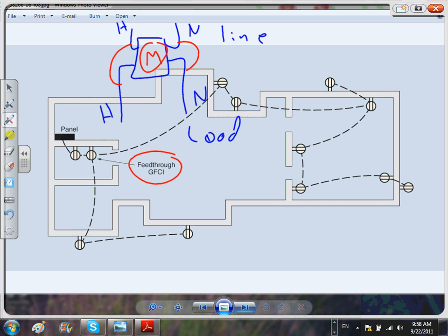At the time, it wasn't finished. Now it's completely finished, and there's a GFCI receptacle, and there's equipment behind it. From that GFCI receptacle in the basement, he fed through a receptacle outdoors, which is okay by code. So the GFCI receptacle in the finished basement with a lot of equipment behind it tripped. The owner doesn't know that there's a GFCI. I should have thought to tell him, but he said it's a finished basement. I didn't know when it was wired.